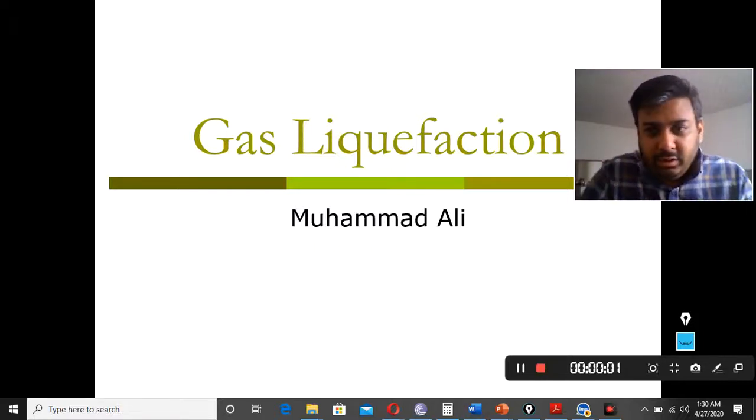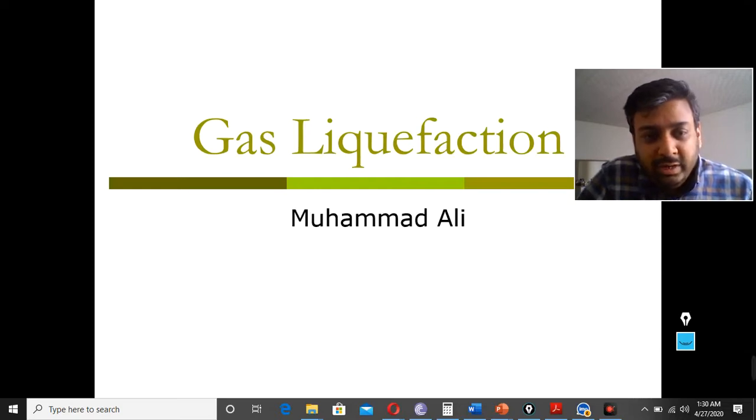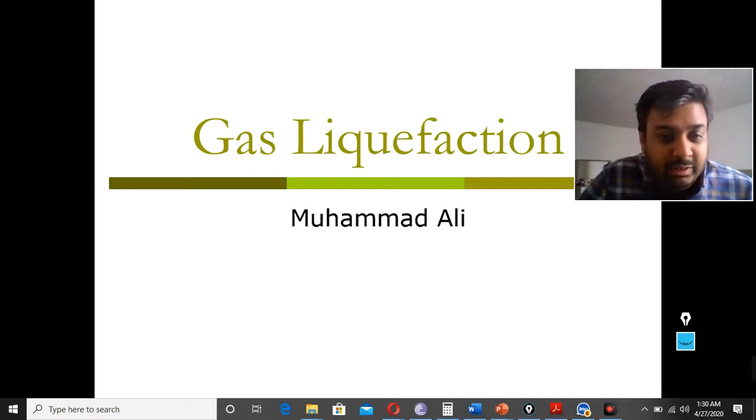Hi everyone. Today's lecture is about LNG, which is liquefied natural gas. It is methane gas, the same gas we have been talking about, but in liquefied form. What we do is play with its critical properties. We reduce its temperature to minus 161 degrees centigrade, a cryogenic temperature, and convert it into liquid. Then we transport it, and then we gasify it. That's the procedure.